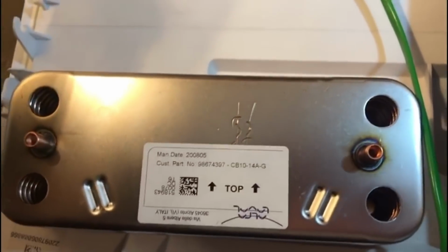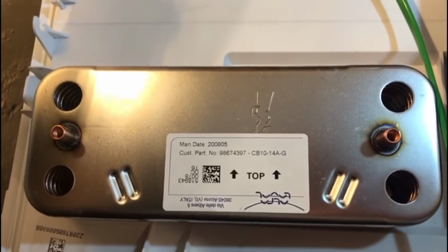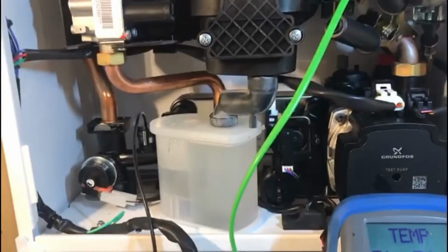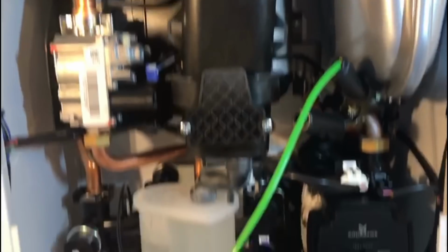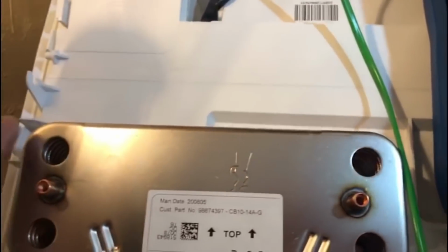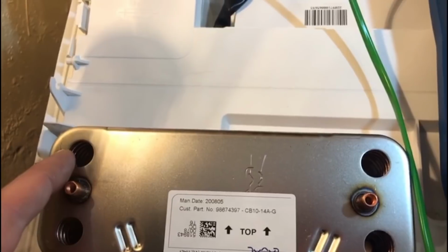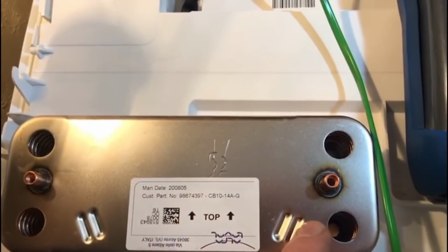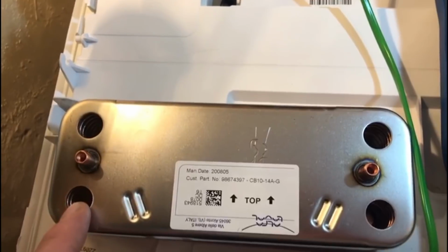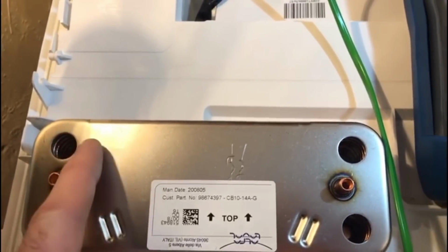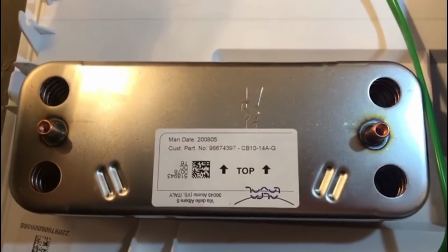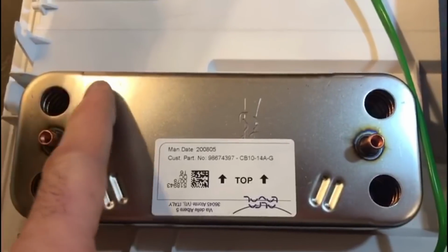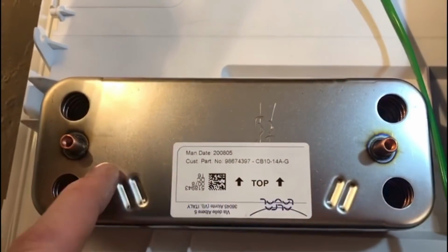The reason for this is, let's say for instance around about 80 degrees coming out of the flow of the heat exchanger, the top of the heat exchanger, flowing into the plate heat exchanger. If we're picking up 35 degrees across here and out of the hot water pipe, we're going to have to lose 35 degrees across here. Effectively, this is a heat exchanger, so it exchanges the heat. So we're going to lose 35 across here, pick up 35 across here.